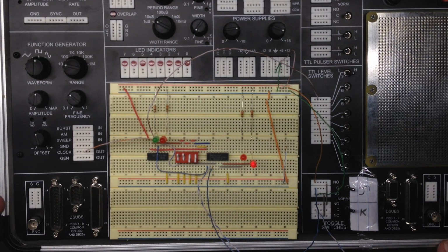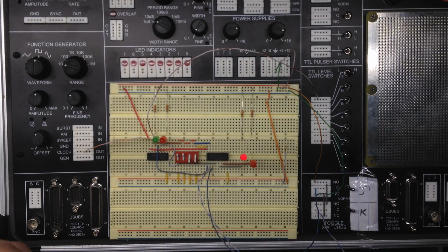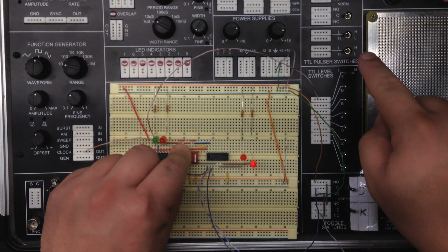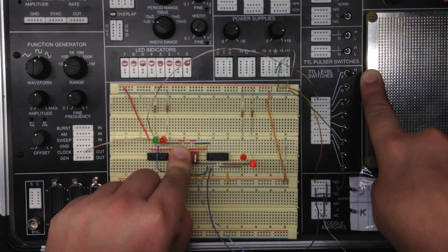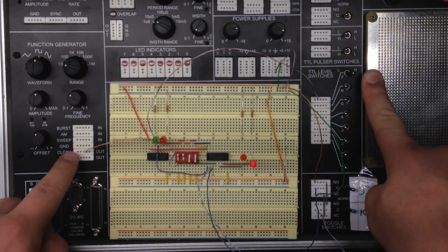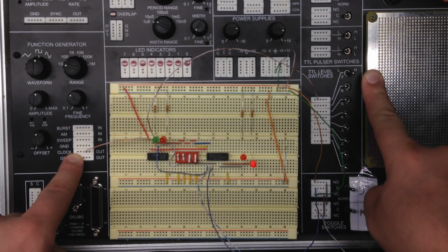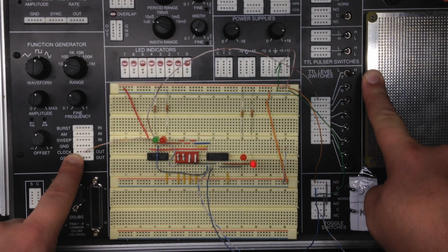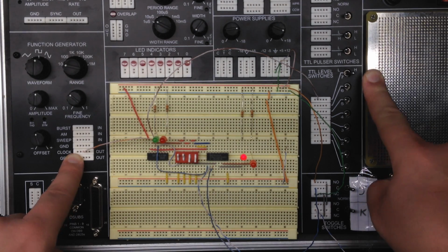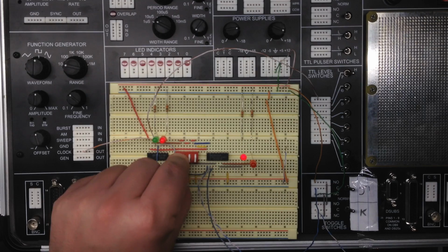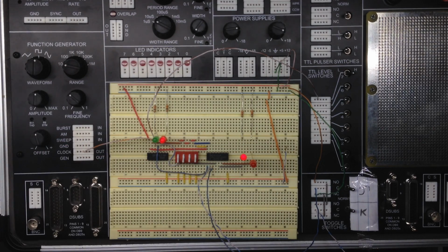What will happen is whenever we turn both of these back off, it is going to go back to whatever state would be represented based off the current state of the IC and the inputs. So when we flip these back off, we have a high on the TTL switch, and we have the clock coming in. This will give us a high on Q and a low on Q naught, which means our red LED should come on. We see that that happened.